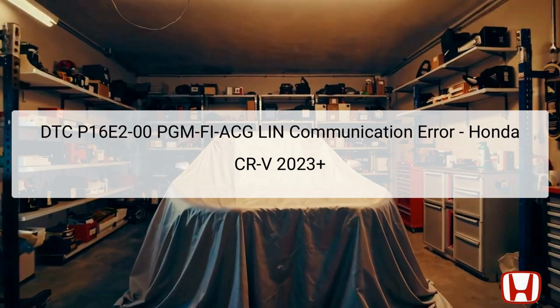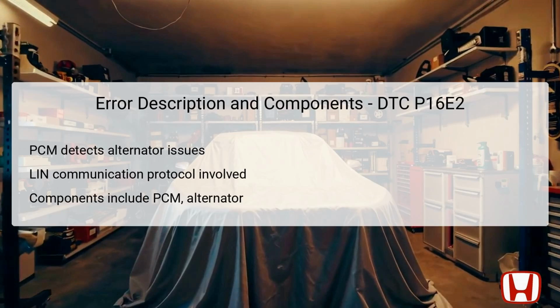You can diagnose the problem following specific troubleshooting steps outlined by the manufacturer to pinpoint the exact cause of the error. The P16E2 error signifies that the Powertrain Control Module, commonly referred to as the PCM, has detected issues with signals being communicated from the alternator. The primary affected component in this scenario is the alternator, which plays a pivotal role in charging the vehicle's 12-volt battery while generating energy for various electrical systems.